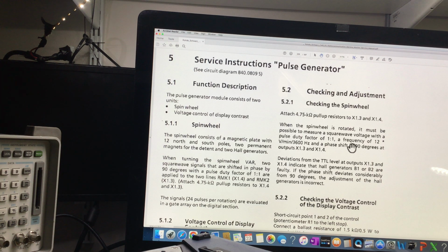When we spun it really quick, it seemed to clear itself a little bit so that it behaved, and then as we just adjusted it a few notches or detents one way or the other, within a quarter of a full turn it started playing up again. So it could be that there's iron filings or some foreign debris in there that's magnetic, that's sticking to things that it shouldn't be, and it's giving a false signal,